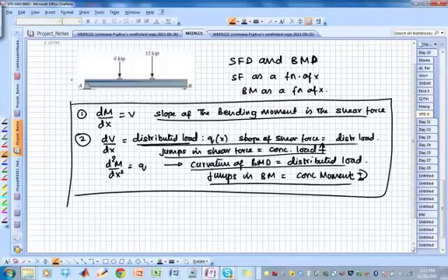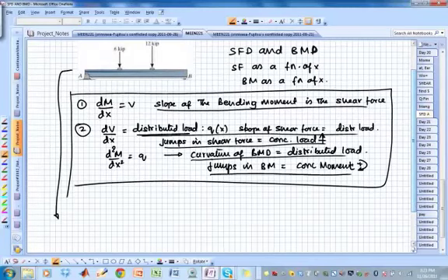So I want to find the shear force and bending moment diagram for this. In order to do this, you need two things. Get your trusty calculator out, get a ruler out, because we are going to draw this in a fairly careful way, and it's better to do it on engineering paper so that it's easy for you to draw the pictures to scale. Okay, so the first step is to mark the axes, y and x. So that's step number 1.